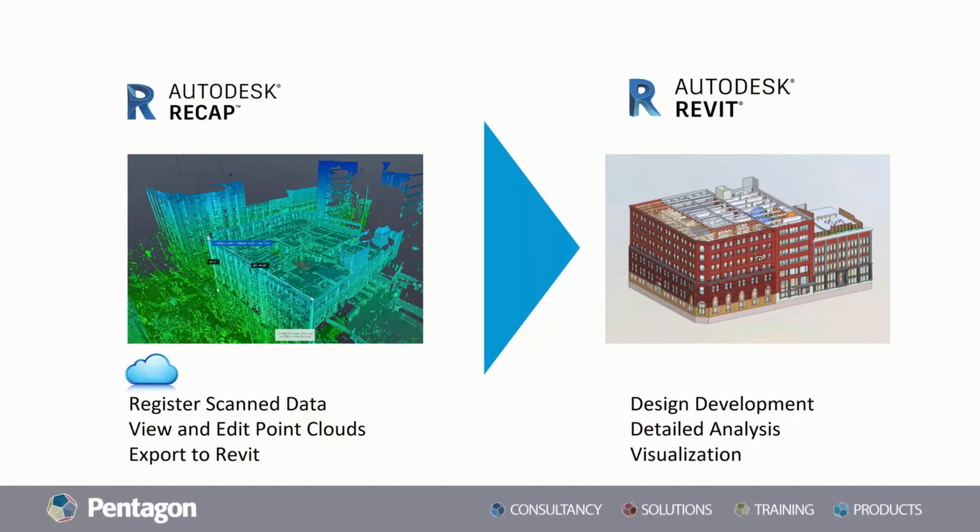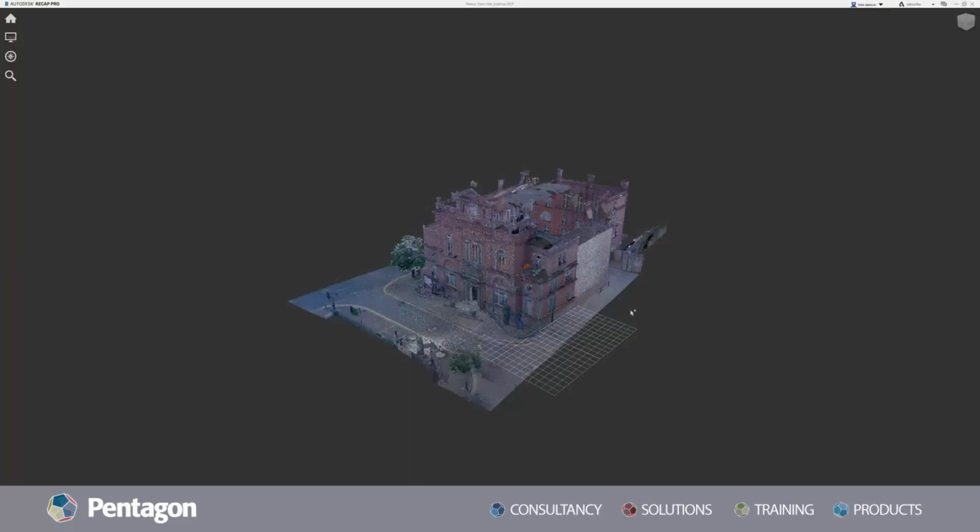So you can see there on the left hand side there's a point cloud model and how that's been brought into Revit. There are automatic buttons already built into Revit. If you go to the Insert tab at the top, you can just click Insert Point Cloud and it'll allow you to bring a Recap file in. After that, you can pick those individual point references again to draw along them using walls, floors, whatever's necessary.